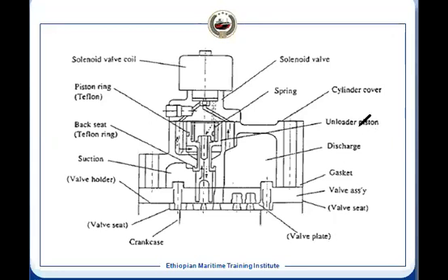So we can have oil operated, like we have a piston, and this is the spindle which is pushing the valve in open position, and there is an oil pressure acting on it. There is a solenoid valve which is a control valve. It means in normal condition it will be drained, and in normal condition it has to be in open position, that is the unloaded position,